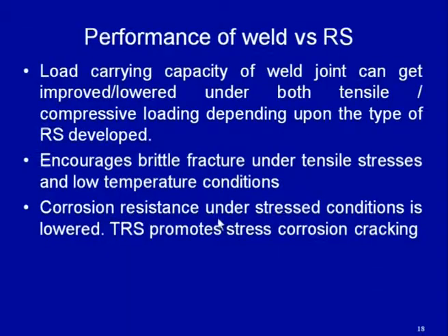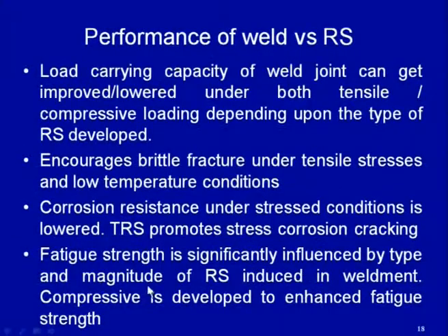The corrosion resistance under the stress condition is also lowered, and the tensile residual stresses promote the stress corrosion cracking tendency. Further, the fatigue strength is significantly influenced by the type and magnitude of the stresses being induced in the weld joint, and compressive stress is developed to enhance the fatigue performance. So, it is common to use the techniques which can help in developing the compressive residual stresses in the weld joint, so that the fatigue performance of the weld joint can be improved.